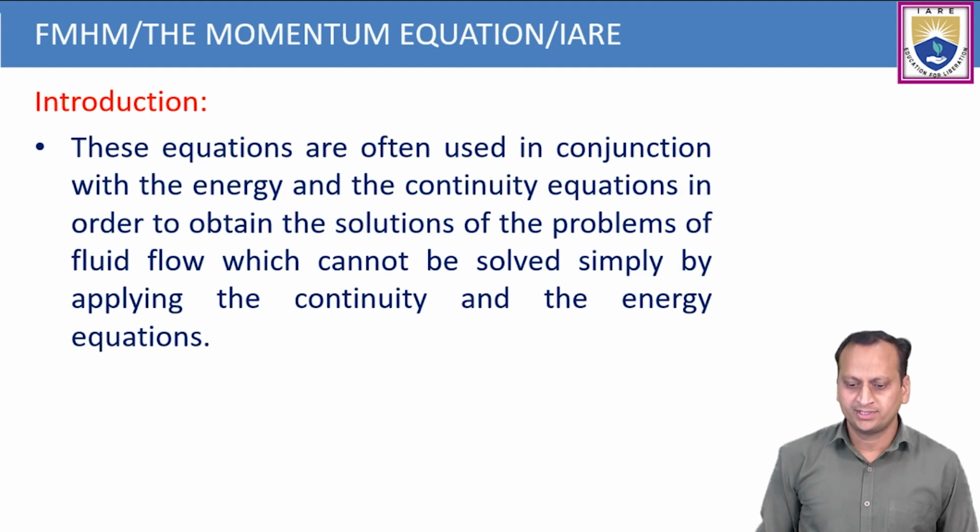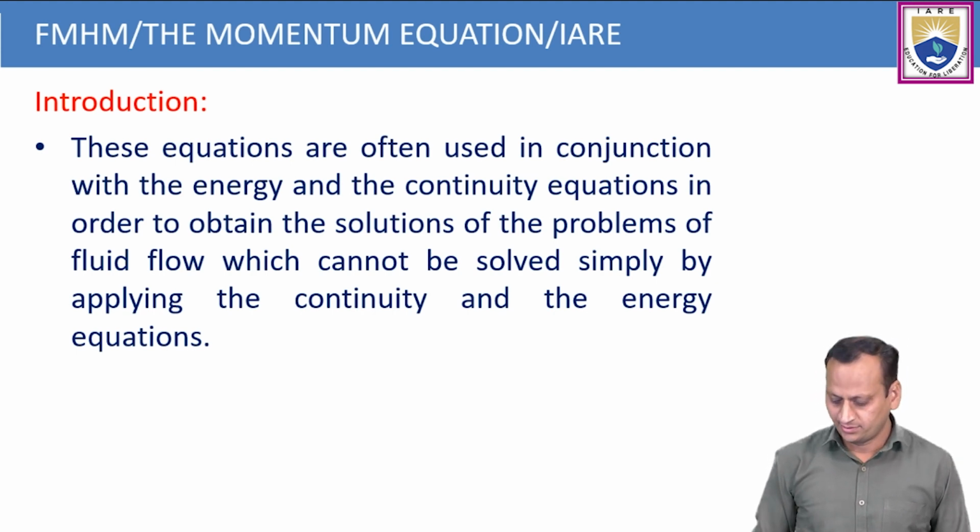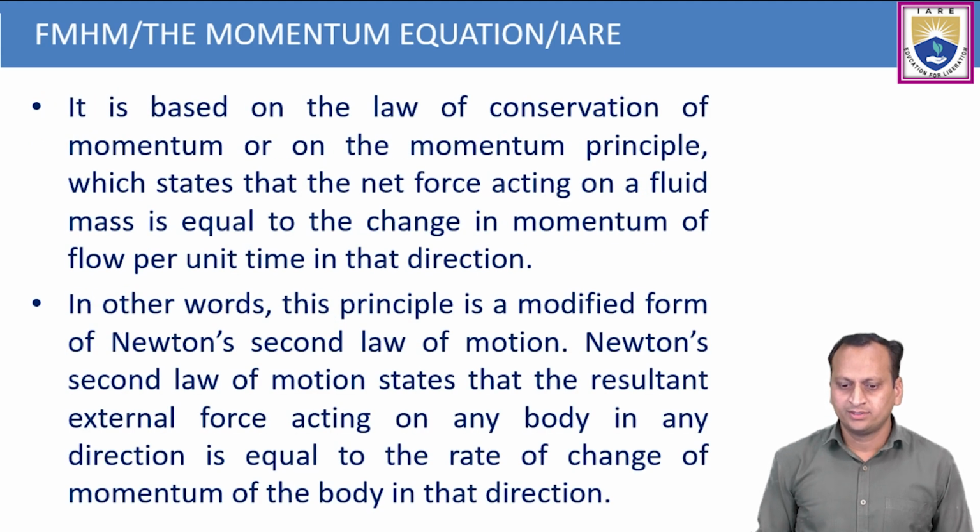So these equations are often used in conjunction with the energy and the continuity equations in order to obtain the solutions of the problems of fluid flow which can't be solved simply by applying the continuity and the energy equations. It is based on the law of conservation of momentum, or the momentum principle, which states that the net force acting on the fluid mass is equal to the rate of change of momentum.